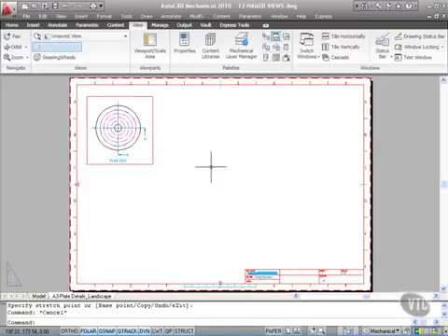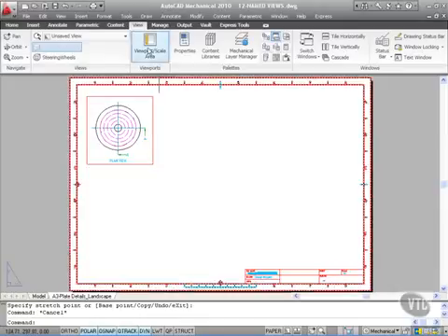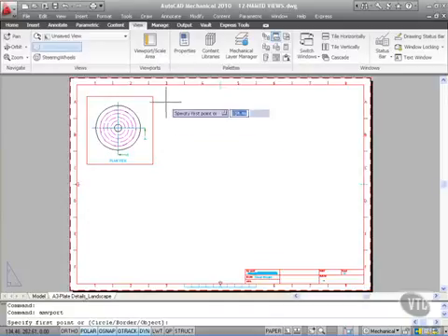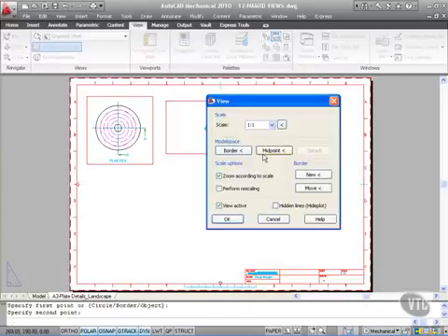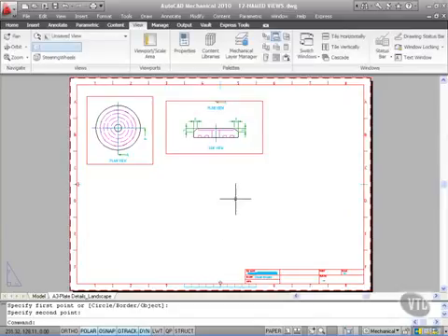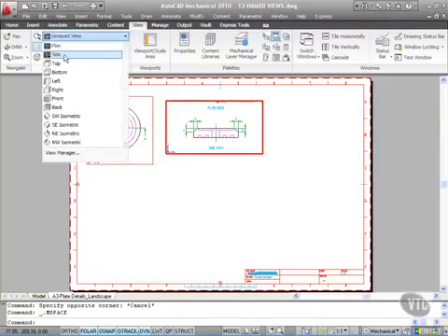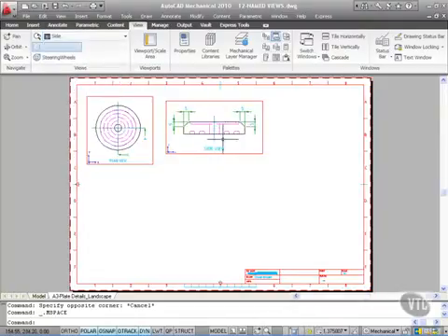Slightly more traditional way of doing it, but it still works. You'll notice though that scale areas tend to be quicker as per the previous exercise. So that's utilising named views. We'll do one more quick view there. So again, viewport scale area. I'll click and I'll drag like so. Set the scale there, 1 to 1. Don't need to do that. I'll just click on OK. What I do now, double click inside the viewport, find my side view here on the list. There's my side view there.